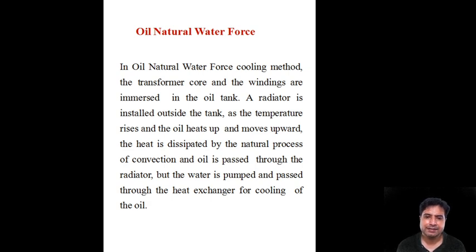A radiator, we fill the radiator with cool water, and air blows through this radiator and cools off the engine of the generator or DG set. So exactly in the same manner here, oil natural means oil is not forced, and what we have is water forced. So cooling water is used in this method. The transformer core and the windings are immersed in the oil tank. As it happens with a normal transformer, a radiator is installed outside the tank.